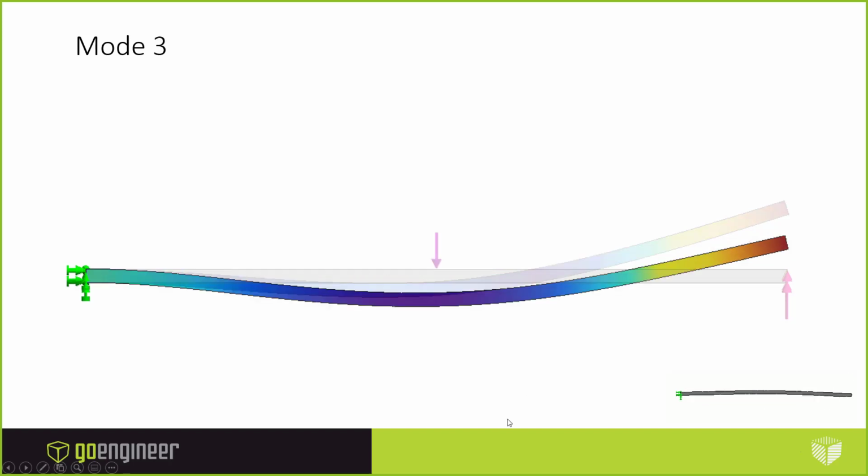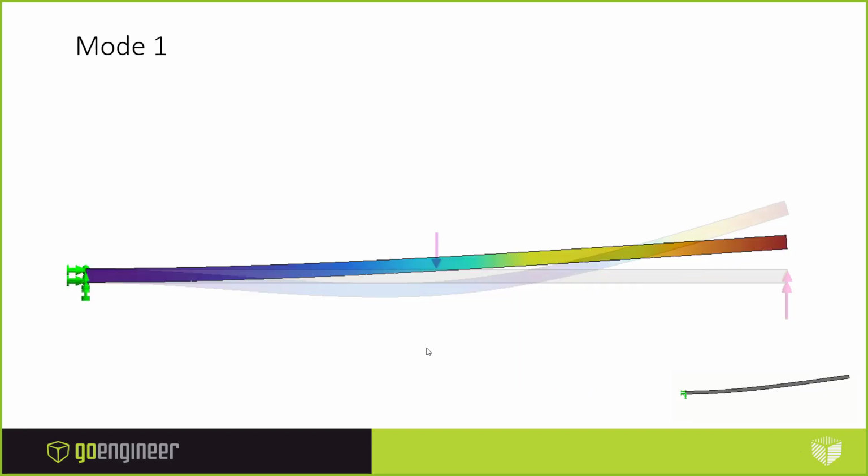Let's look at another mode though. What about mode 3? It looks similar to mode 3. You can see the original shape here in transparent in mode 3, but it doesn't match that one either. And if I just scale that one up, it won't really work. If I scale it up to be twice, it might match there, but then this one will be even lower. So it doesn't really match either of these modes perfectly, but what I can do is take mode 1 and mode 3 and add them together.